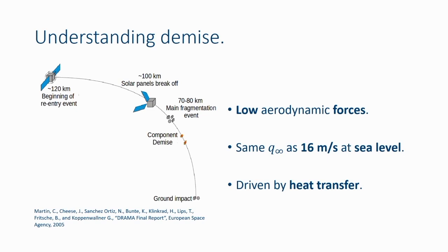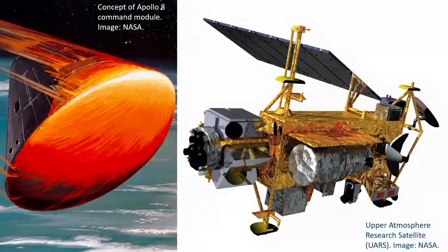rates to hypersonic shapes. And you're right, but most of these correlations were developed for shapes like this on the left, right? There's a nice round shape. It's axisymmetric, hasn't got any sharp edges, hasn't got any flat surfaces. This is something which you can find an analytical solution to the Navier-Stokes equations for. This is what a satellite looks like. So I'd argue that whatever correlations we have for this, we probably can't use for a shape that looks like this, right? We need new correlations to describe the heat transfer rate to a faceted shape.